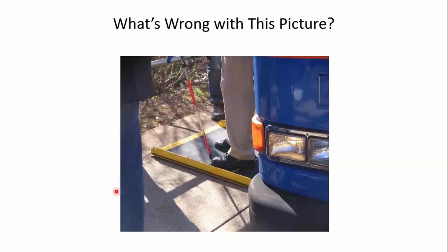Fortunately, in this case, probably about 50 feet to the lower left, the sidewalk that you see here widens to about 20 feet wide. And so what the transit agency was able to do was just shift the bus stop probably 50, 75 feet down the street where they could make an accessible stop. But that's something to consider in developing transit stops, is make sure the stop is accessible depending on the mechanism the bus uses for accessibility.